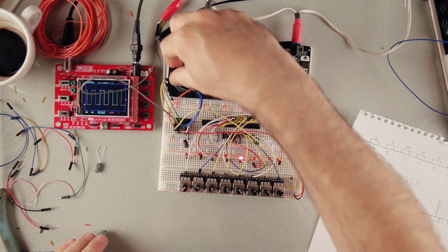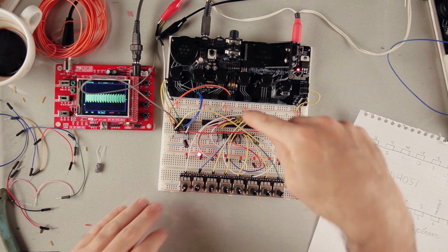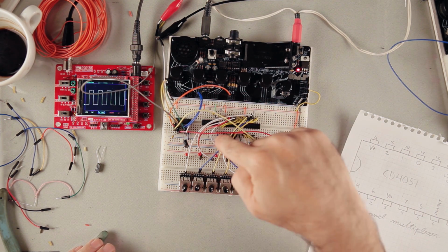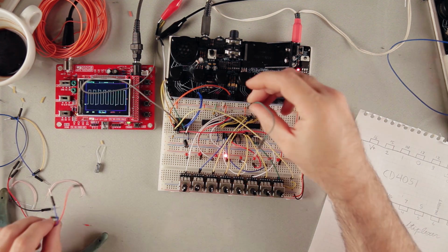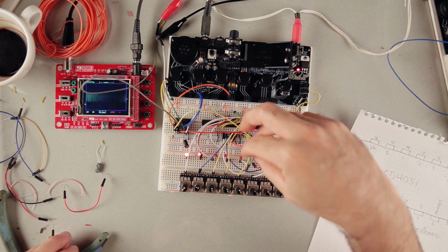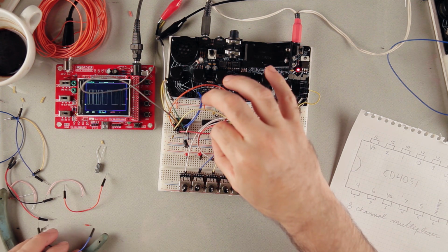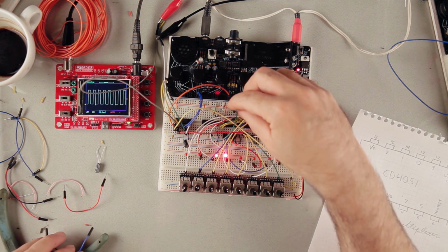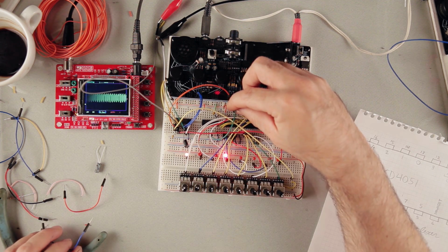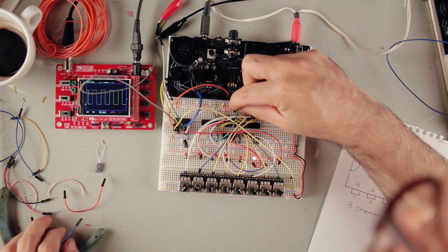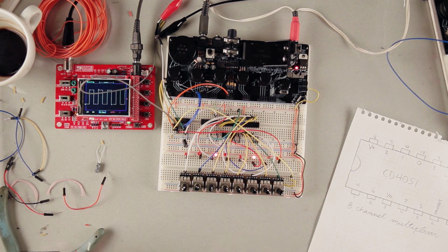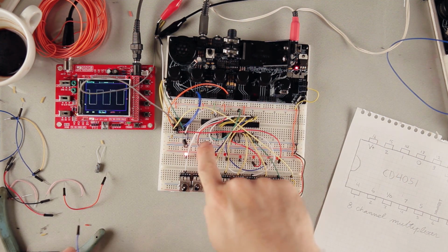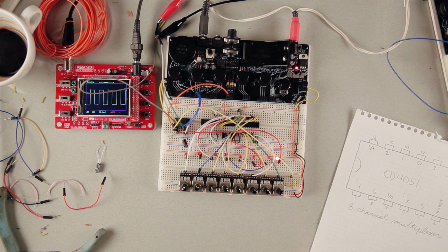So we have the sequence, which is coming from our binary counter. The outputs of the binary counter are plugged into the data inputs. But we can connect those data inputs to other outputs from our 4040. So let's see. There we go. So now I've taken a different bit, one of the divisions. So let's get our 4040 sheet.